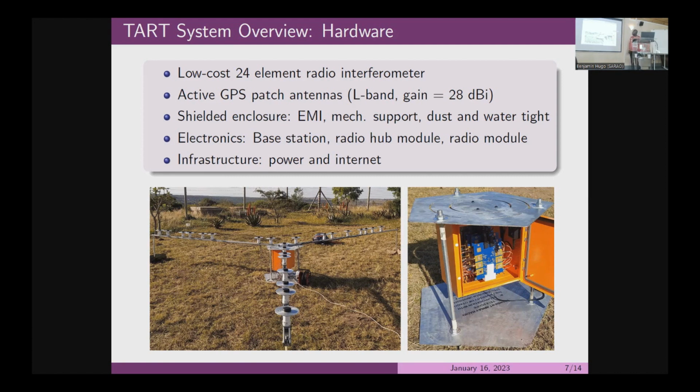Then we also need to do conducted emissions, like within the antenna structure and the cabling here. I will show you how we can do that. How is it properly connected, or do we have radiated emissions that get converted to what is known as unwanted common mode currents, and that can happen in 2 ways. 1, because of the coupling of the cables. 2, because of the radiation elsewhere that couples into the cables. So that is also another student project.